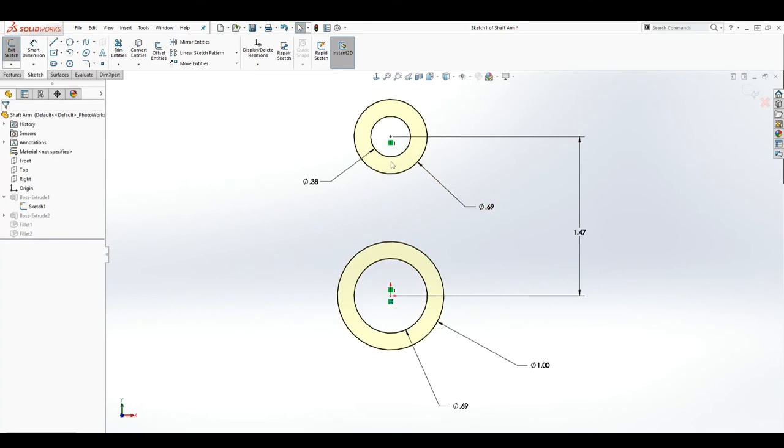Let's say you've modeled your part. I've made this part now, and let's say I decide that this dimension is different now, and I just want to change it. What parametric means is the dimensions and the relations allow us to go back into the sketch we've already made and easily change it, and it will be automatically applied to our part. So I'll just show you.